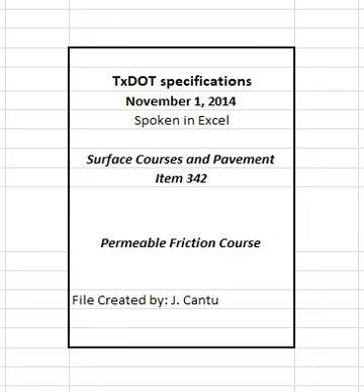4.1 Certification. Personnel certified by the department-approved hot mix asphalt certification program must conduct all mixture designs, sampling, and testing in accordance with Table 3. Supply the engineer with a list of certified personnel and copies of their current certificates before beginning production and when personnel changes are made. Provide a mixture design developed and signed by a Level 2 certified specialist. Provide Level 1A certified specialists at the plant during production operations. Provide Level 1B certified specialists to conduct placement tests.